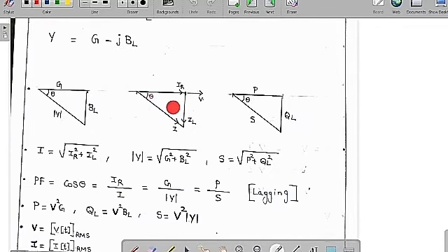Because the voltage is the same across the two elements, as they are in parallel, we take the voltage as the reference in a parallel circuit. You can see clearly that in a resistor the current IR and the voltage are in phase. But in an inductor the current is going to lag the supply voltage. If you want the net current, just do the vector addition. This is called the overall supply current.